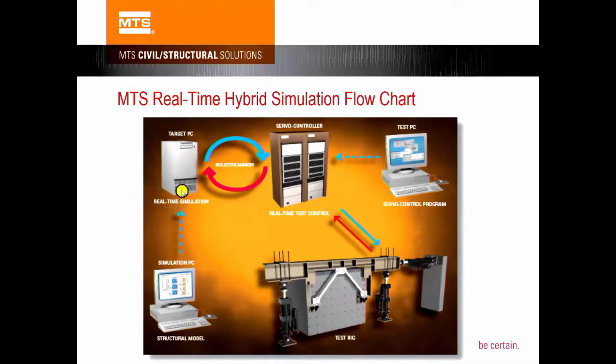Also, the command can be sent to the controller and stored really fast. We use a SCRAMNet card to store the command, use a fiber optic cable to transfer the command to the controller, and then use a fast actuator to realize the command in real time.